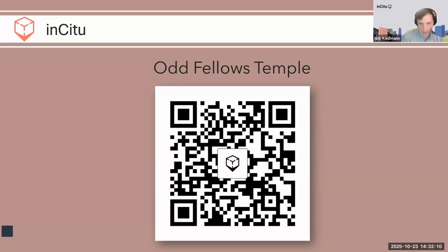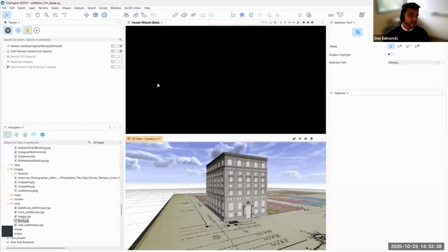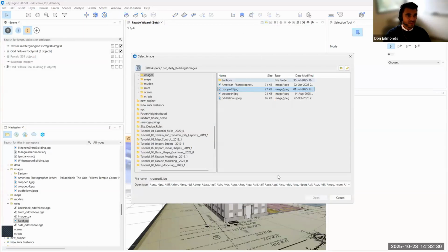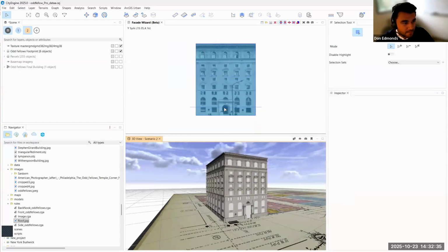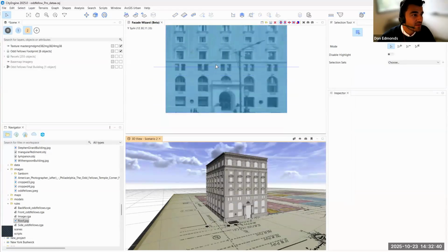Explain a little what we're seeing in AR here. So the roofs and the sides were not referenced in the photo. Can you remind us how you got those? Yeah, so when you're within the Facade Wizard, within City Engine, and you have your image, what you can do is essentially create a split. Sorry, I'll show you here. We have these different Y splits, X splits.